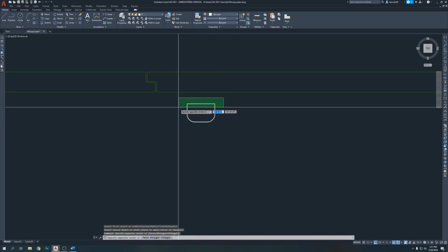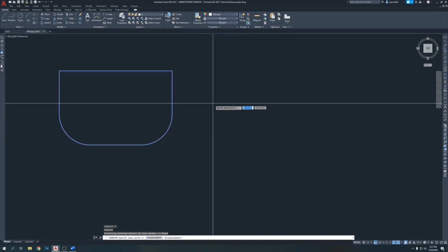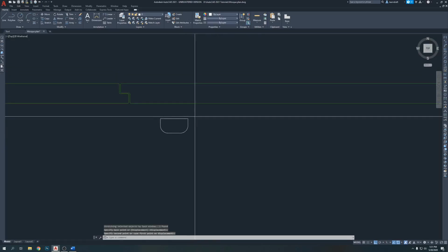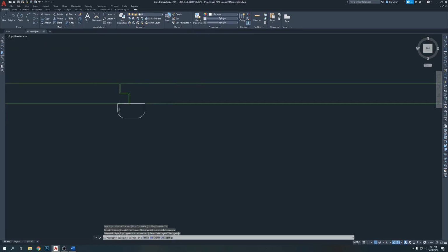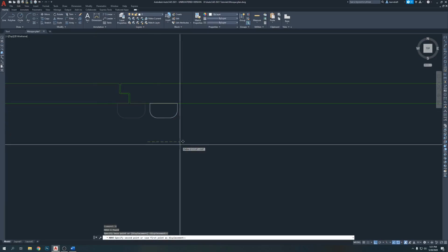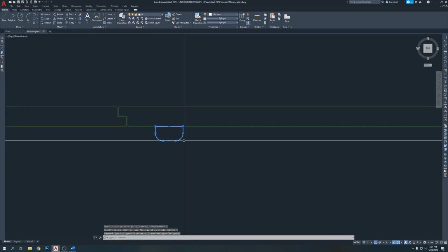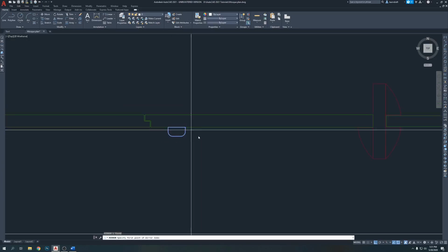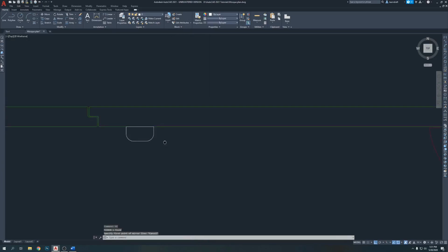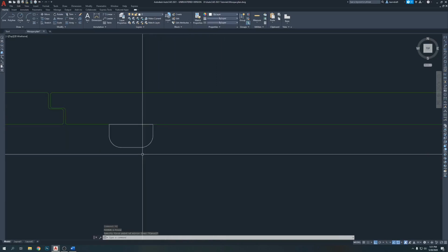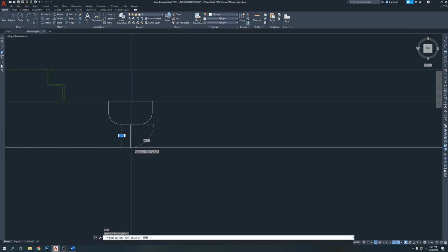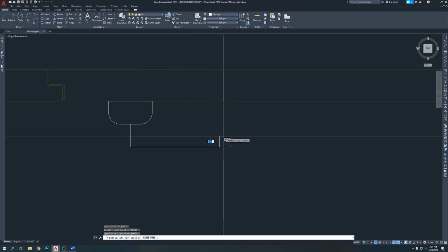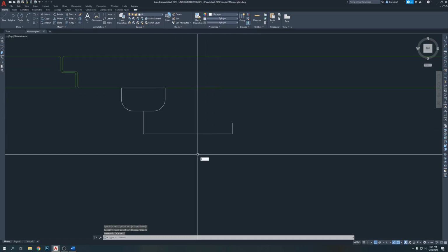It's a little bigger. Let's bring it a little bit down. Yes, I'm actually making a handle. Hold it, put it there, and bring it like, yeah, 4 inches is good. It's too big? No, it's good. And L, bring it here, and bring it there, and bring it there. Now fillet them.